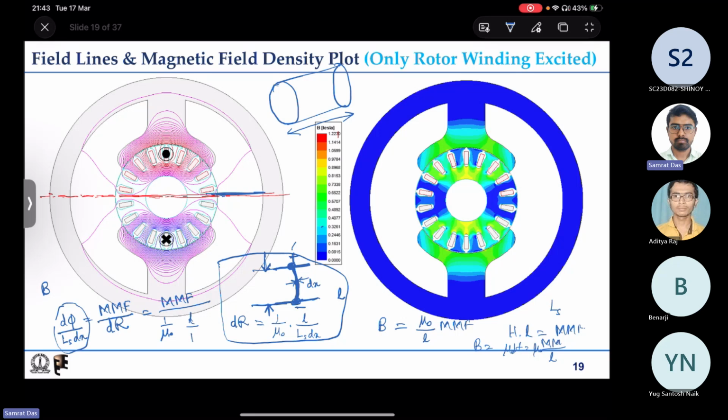So what have we achieved by this discussion? At any point, if we know the mmf drop between two surfaces, and if we have an approximate expression for L, the length of flux line between the two surfaces, then it is possible for us to calculate B.